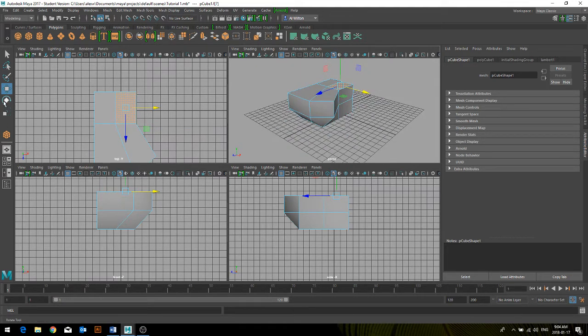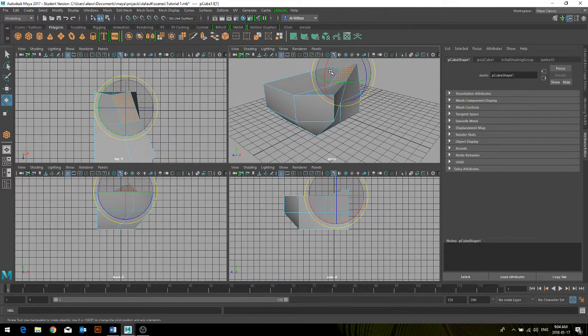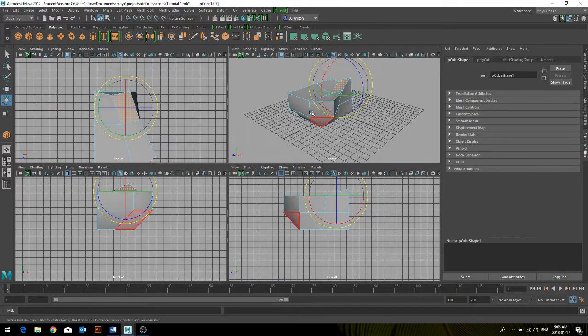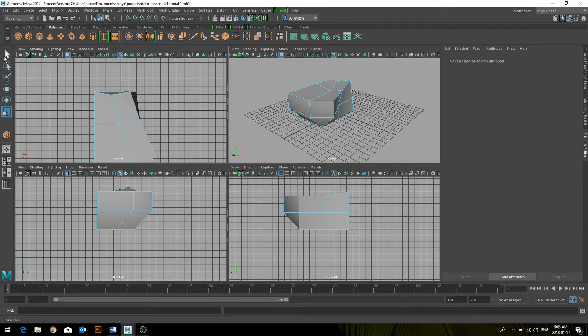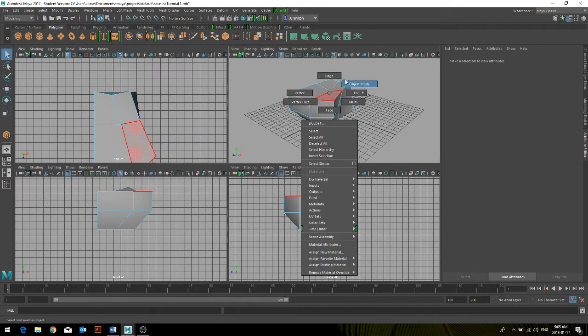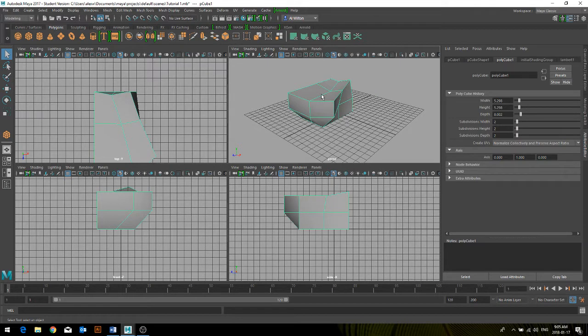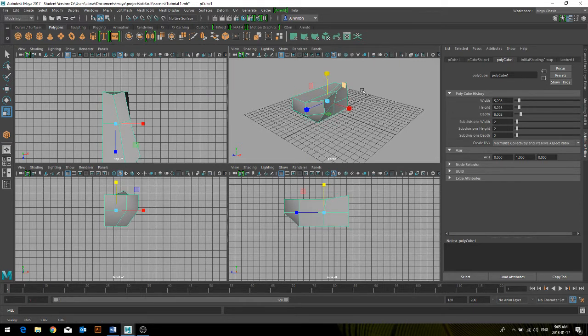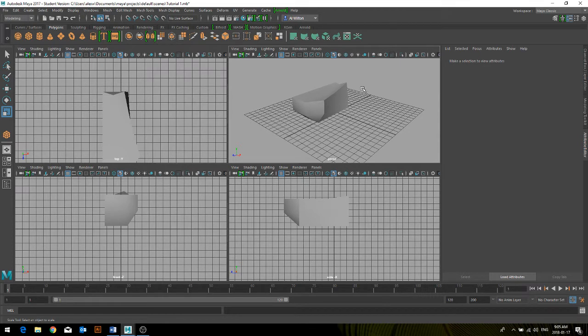So if you go into rotate, you can kind of move the polygon around in strange ways and scale individually by face, or if you wanted then to go back and right click into object mode, you can take the entire object itself and begin to scale it as a whole polygon.